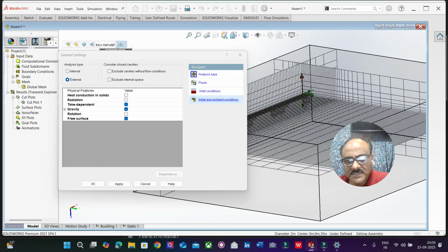And now I am going to define a free surface, because there should be a partition between water and air. I told you the air which is moving at a certain velocity is going to impart that force onto the water. And how does it impart a velocity onto the water? The air which is flowing is going to create a shear onto the water surface. The top layer of the water is going to shear with the second layer of the water, then with the third layer. So likewise, this entire blanket of water is getting carried to the next part.